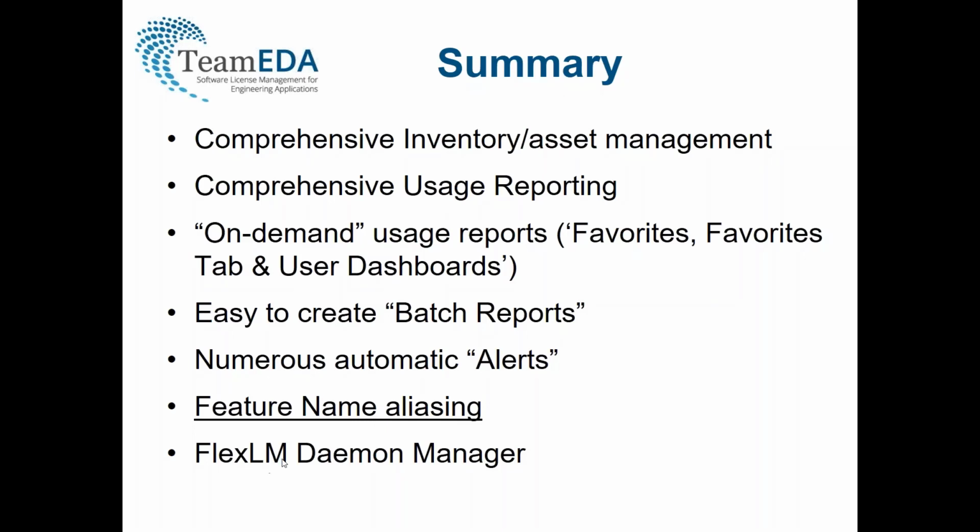The tool includes a FlexLM daemon manager so that you can deploy, start, stop, restart FlexLM daemons. You can edit license files, option files, and debug logs with this tool. And if you're using option files, we have built-in syntax checking.